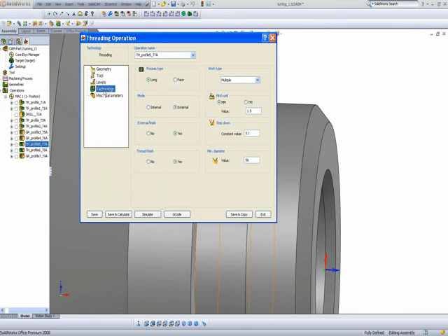And in my technology, again, I'll be working along. I'm doing an external thread. And I want to have finishes on the corners itself, on the threads itself. And my working type will be multiple. In other words, not one pass, but several passes until I finish down to the bottom.